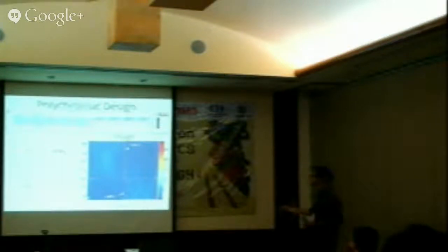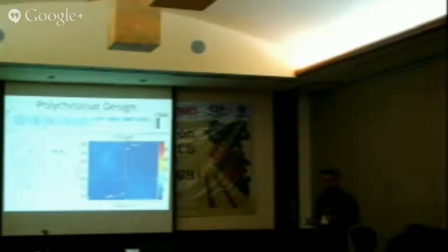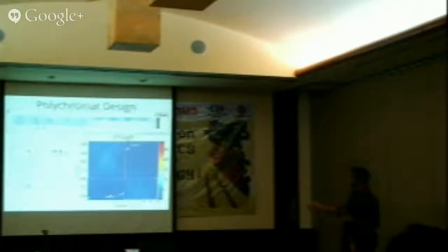So an example of a design is shown here where we take a cross section, and it's very complicated because it's designed using a linear optimization. But if you zoom in a little bit, you can see what they are supposed to look like. They look like little staircases, right? Little structures. But they're multi-level structures, and they're complicated. Okay? And we pick these sizes to be something that we can fabricate easily. This is about 10 microns. Nowadays, the examples I show you, we've made them down to about 3 microns. And this height is typically in the order of 1 to 3 microns total.